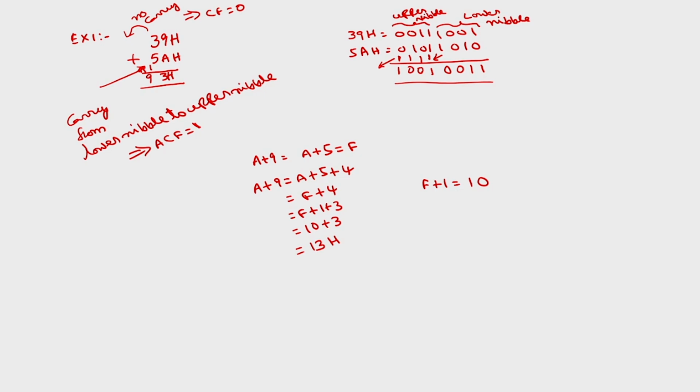There are two instructions, like decimal adjust accumulator, DAA. While discussing the instructions, we will see this auxiliary carry flag will be used in this instruction. Similarly, we have decimal adjust after subtraction. These two instructions will use the auxiliary carry flag. Coming to the fourth conditional flag, which is the zero flag.